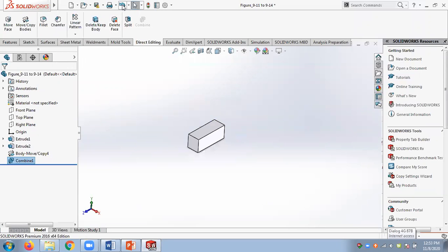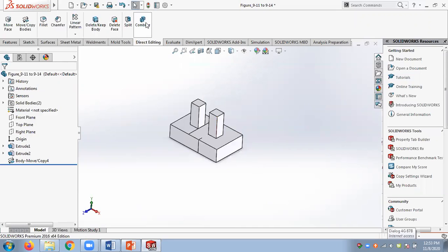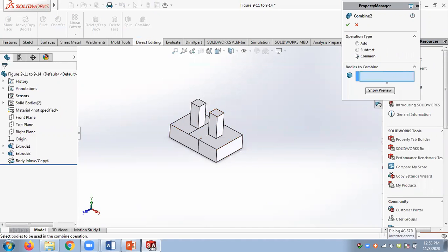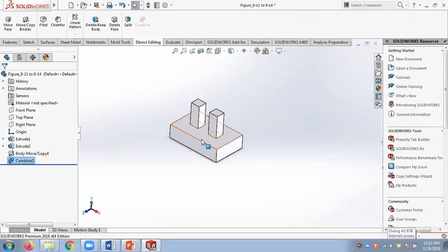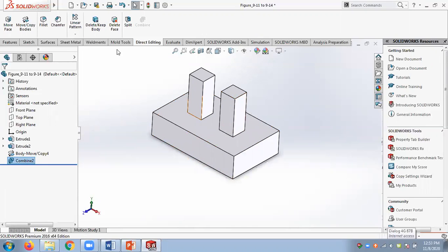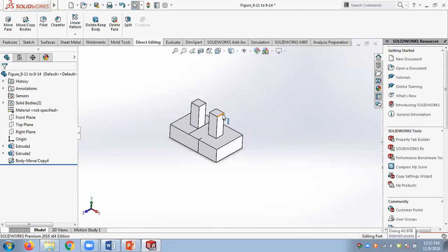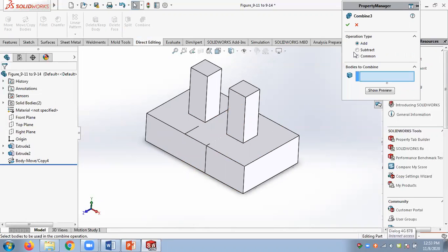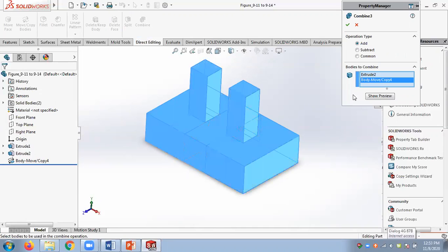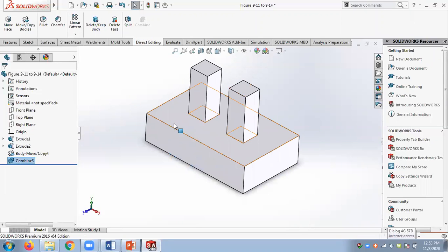Okay. So this is another way of doing SolidWorks. You can have several bodies, and you can add them. Now, if you add these two bodies, it will become a single body. So you can see the splitting lines have disappeared. Earlier, you had these parting lines, splitting lines. Now, when you combine the two bodies, it becomes a single body. No middle lines, splitting lines.